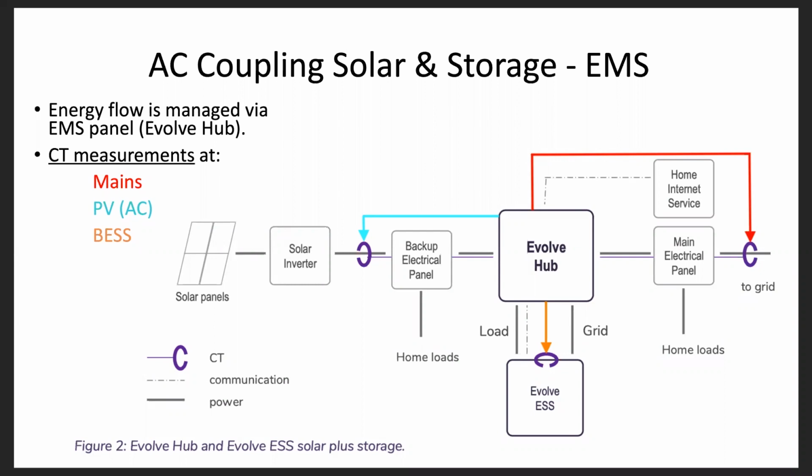So it does have power factor control from 0.8 lagging to 0.8 leading. It does comply with all the advanced inverter controls and reactions required in California Rule 21A, all the way up through the phase 2 and phase 3 communications controls. So it does have quite a bit of capability built into it.